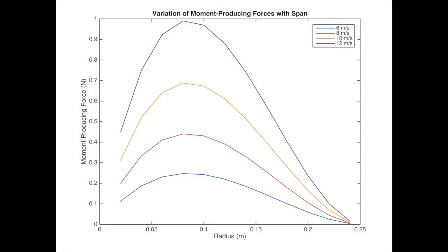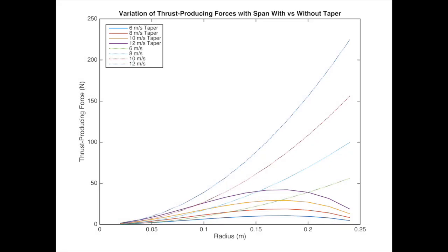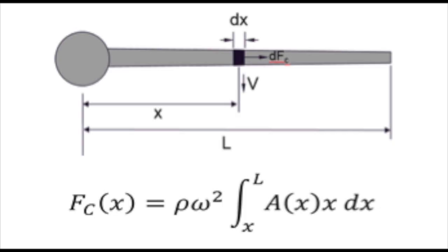So where do these stresses come from? Stresses in the blade arise primarily due to tangential and thrust forces that result from aerodynamic forces of lift and drag, and also from centrifugal force, which becomes very important at higher RPMs. Considering all of these forces, we analyzed the stresses on the blades on the basis of engineer's theory of bending, whereby the blades were approximated as cantilever beams.